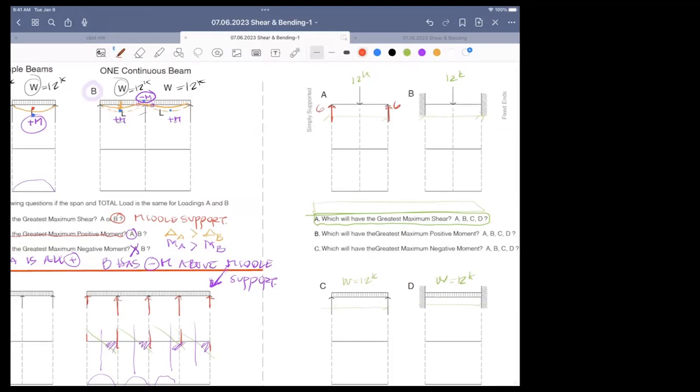And the 12 kip uniform is going 6 and 6, half of 12. And this 12 kip, I know nothing about restrained beams. They're very complicated, but I know that the 12 kip is going to 2 locations. You will take 6, you will take 6. There's moment and all kinds of other engineering stuff. Just ignore it. The 12 kip went to 2 supports. And the same here.